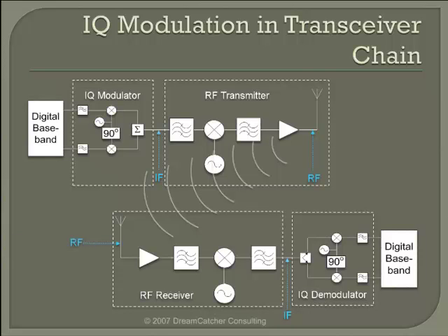The heterodyne architecture enables the rejection of unwanted interferers. For example, the first bandpass filter at the RF receiver is to reject image frequencies, while the second one after the mixer is for channel selection and to reject adjacent channel interferers. There is a trade-off between image rejection and adjacent channel rejection, and to achieve a more favorable trade-off, architectures with two IF frequencies are used.